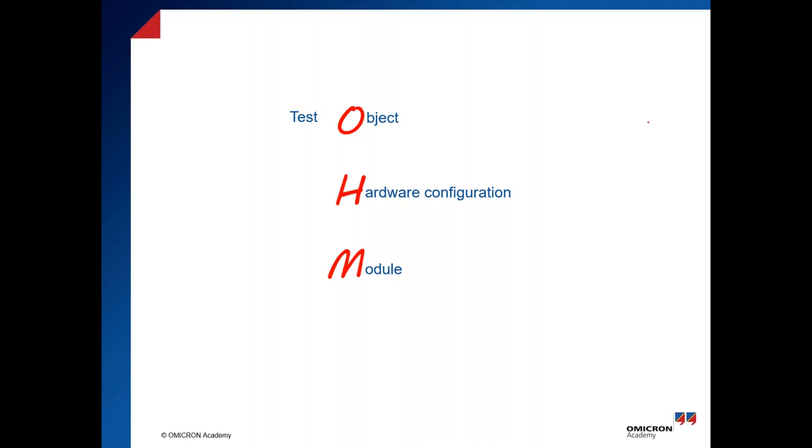After that, we need to select how many test modules you would like to use in testing of that relay. For example, we have numerical relays nowadays, which have multi-functions. For example, overcurrent as a backup with a direction as well, and also the distance protection has some related functions like VT fail, like power swing, like switch on to fault, like teleprotection scheme. All of those protection functions can be tested by using one single file. We call it OCC, which we will talk about later. This can reduce the effort, save your time, and for sure save your money as well.